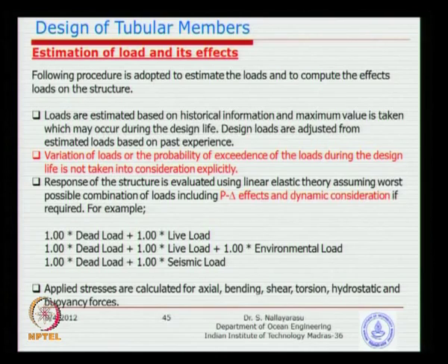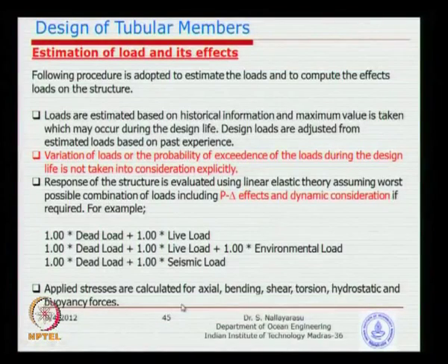For example, maximum dead load, because we are all worried about safety. So, you take the maximum dead load plus maximum live load irrespective of when they are going to coexist. For example, in this particular case, a typical example taken from a code, you take dead load plus live load plus environmental load, all of them taken at 100%, thinking that 100% live load may occur actually at 100% of storm loading, which may or may not exist.